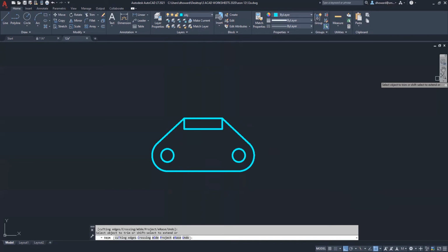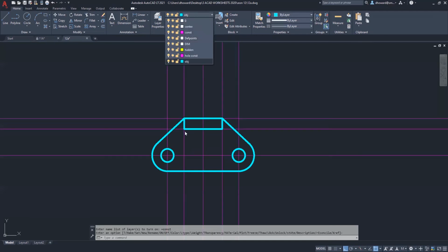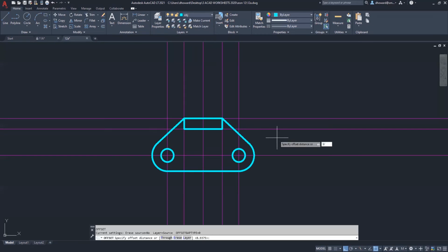It's going pretty good. The only thing I have left to do as far as object lines are concerned is extend this line down a little bit. And that exact distance is 3/8 of an inch. And the reason I have to do that is because there is actually, if you look on the drawing, a radiused support underneath here. So I need to offset this line right here, 3/8 of an inch, 3/8, and then extend this line down to that.